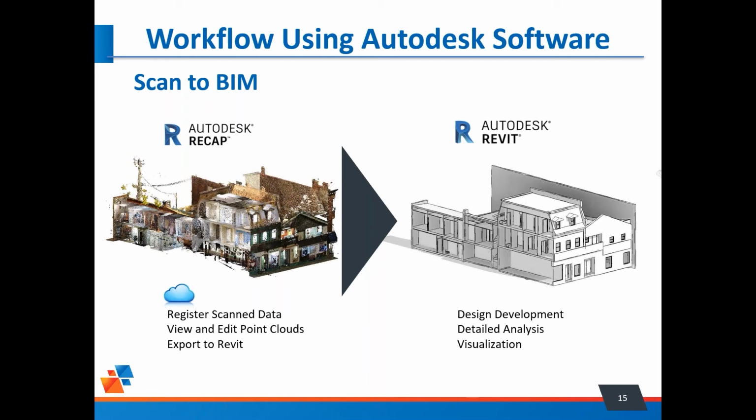We can then export. Actually, it's just really a save. And that is one important thing, that for Autodesk Revit, the only point cloud that you insert or link into Revit is an RCP file or an RCS file. So that's a Recap file. So even with Matterport giving us an XYZ file or just a different file format of a point cloud, we would open that up in Recap and then save it out so that we can then bring it into Revit and create the geometry from that.